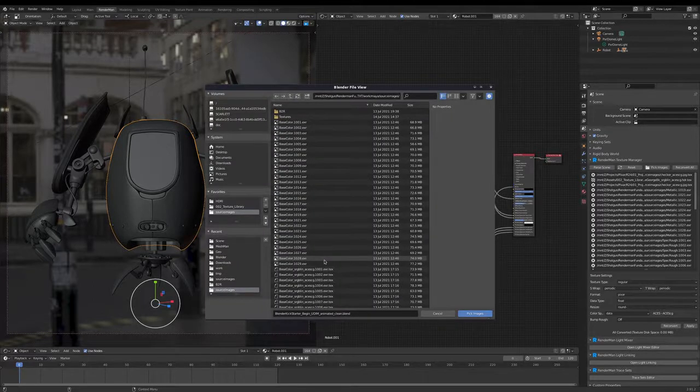So I just wanted to jump in here and clarify why I'm using the texture manager to convert all my textures in this manner. The reason is that I had a lot of EXRs to convert, and to save time in this video, I converted them all beforehand. So it just made life easier for me because I could select all the images, come back a few minutes later, and they were all converted and ready to go. Now you don't have to work like this. You can simply select the EXRs in the Pixar texture node and let the texture manager do its work in the background.